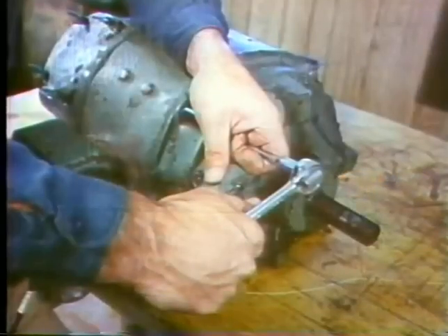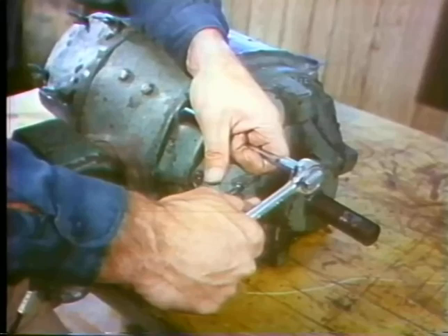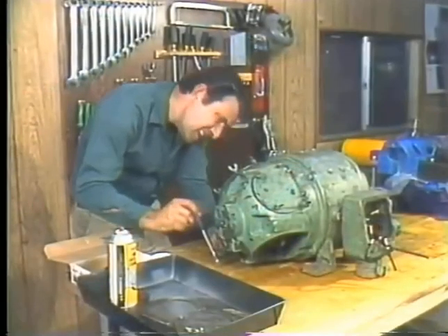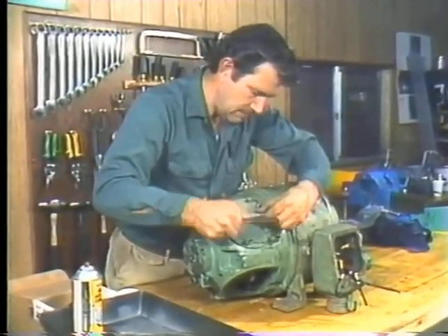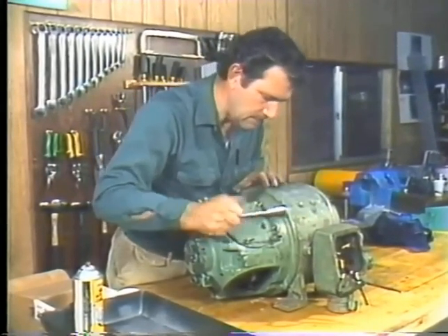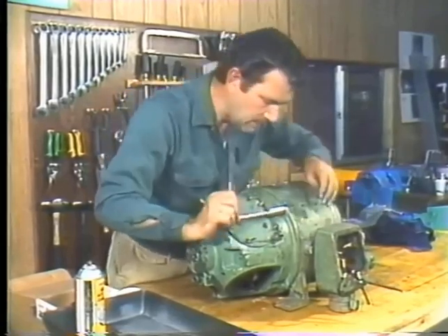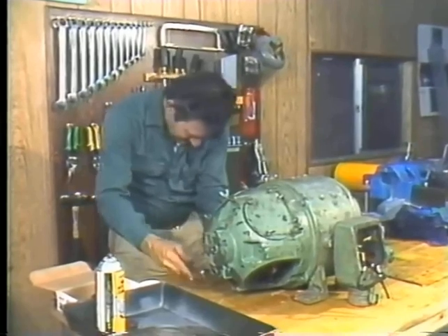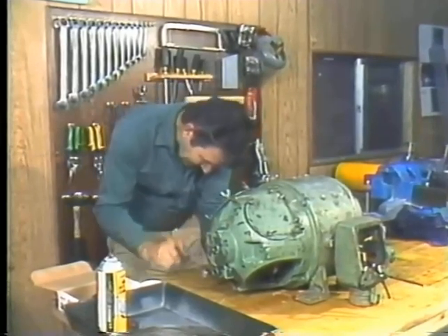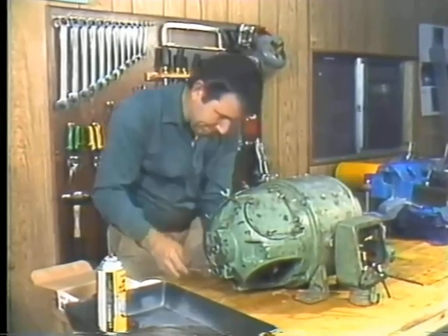Okay, we repeat the same drill with the other end bell. Align it to the frame, tap it in, and snug up the bolts. Now, let's tighten the end bells. To make sure they go on straight, we're going to tighten them slowly, one at a time, in a diagonal pattern across the shaft. A couple of turns on this one, now on this one. You continue the process until each end bell's tight.